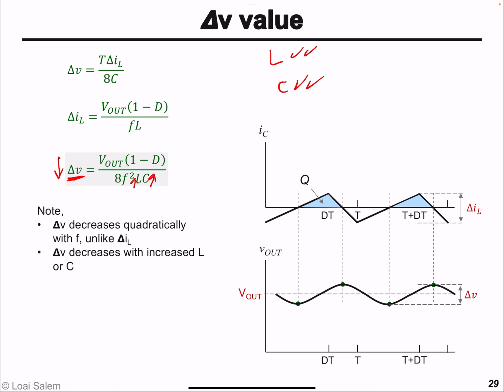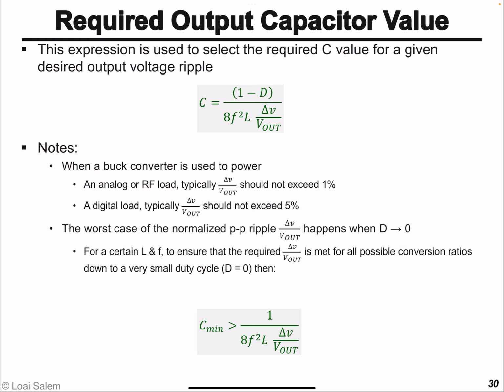Increasing the inductance will require a much larger inductor, which increases the overall volume of the buck converter. On the other hand, using a larger capacitance is better because capacitors are much smaller than inductors in size, as well as weight.